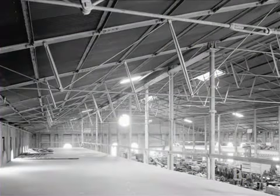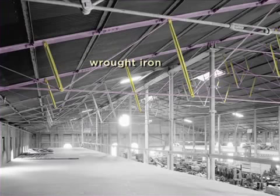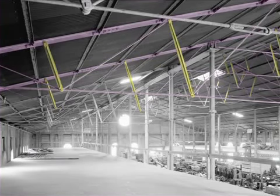And though you can't tell it from this picture, these cruciform members are actually made of cast iron, which was certainly the right choice for a compression member, while the rest of the truss is wrought iron. Clearly, Daniel Badger knew what he was doing.